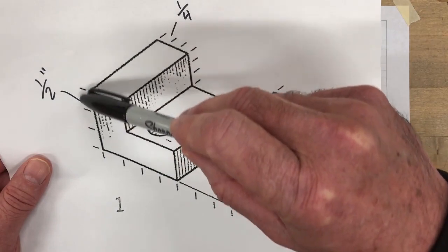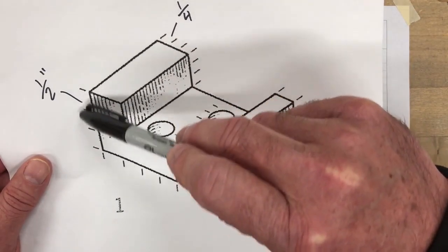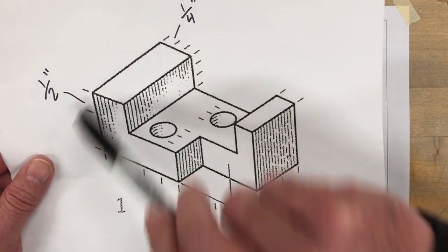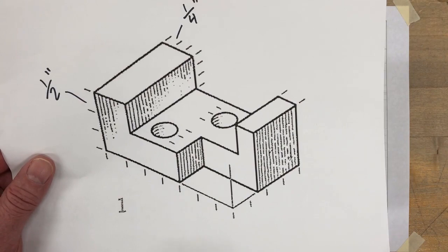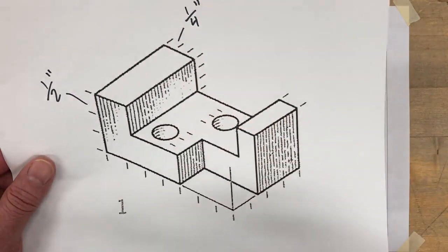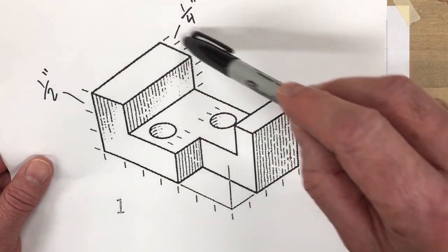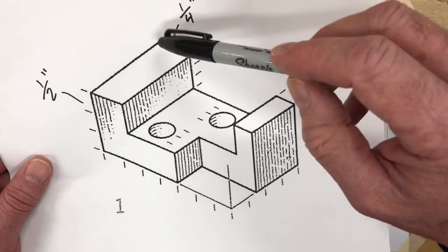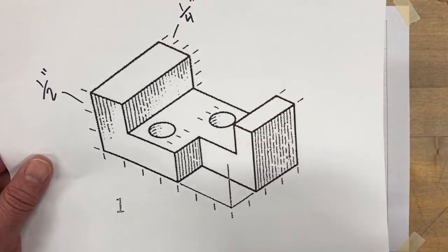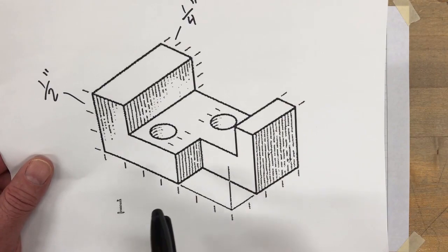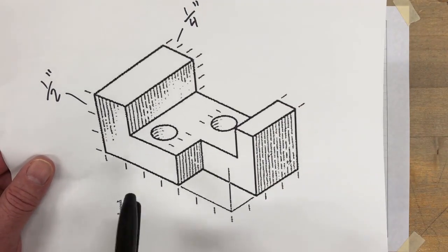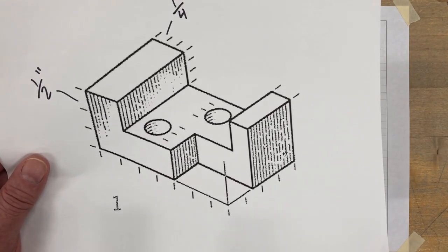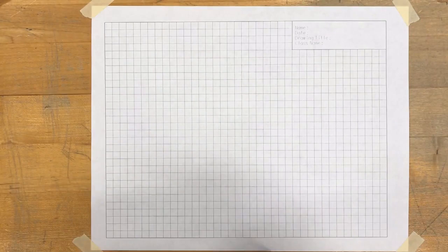This one here, these are what I call large tick marks, and see the distance between there is set at a ½ inch. Those are what we call large tick marks. And it's the distance between the actual marks themselves that I'm talking about, and not the length of them, okay? So small tick marks are, on the other hand, right over here, and these are worth a 1/4 of an inch, okay? And once again, it's a 1/4 of an inch between those two lines. So using this information here, we're going to use this to calculate how long the object is in its overall dimensions. So first thing we're going to do for our drawing here is to create a title block.